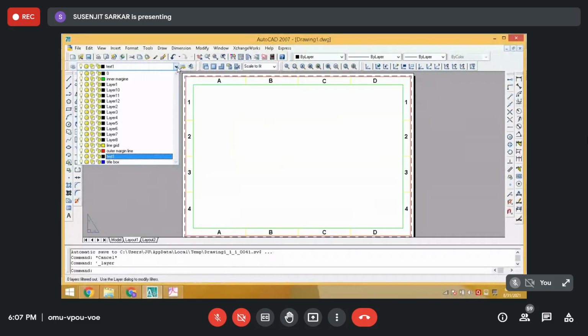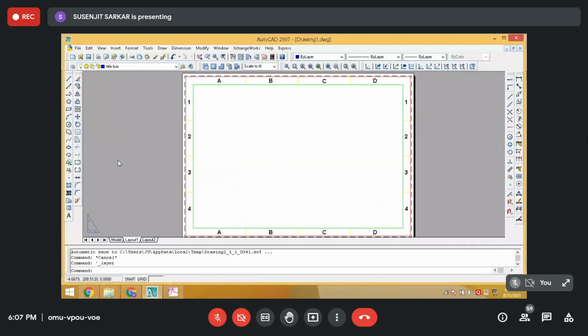Now go to that title box. So the vertical line was 110 by 55, right? I can take a height from any point, snap from this point or from this point. I'm going to draw a line of length 110.